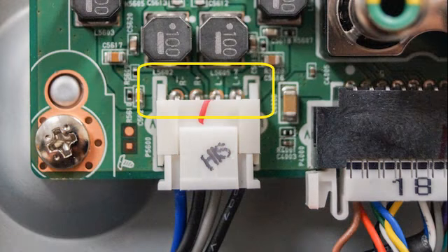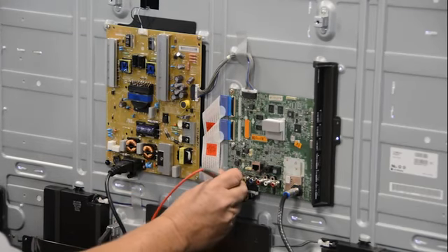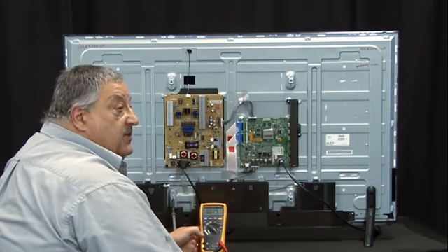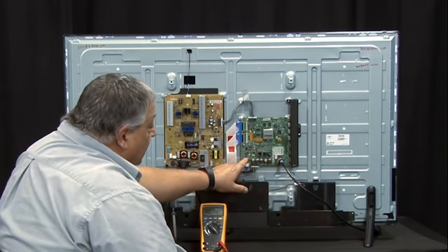Now on the audio output you can pick any pin. It doesn't matter what pin you choose. And you want to look for approximately 1/2 of the audio B+ level on any pin. Just a real brief explanation, we use a push-pull driver out of our audio processor.